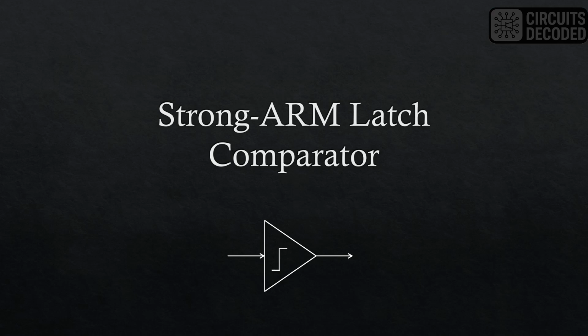The topic for today is the StrongARM latch comparator. It is one of the most widely used comparators in mixed signal designs. Dynamic comparators are usually clock driven and do not consume any static power. It only consumes current at the rising or falling edge of the driving clock. We'll try to understand its detailed operation, analyze its noise, and come up with some design considerations.